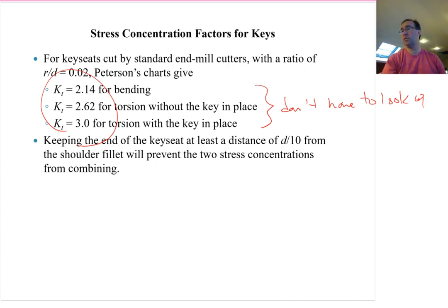Quiz question 6. And this is the other thing, you want to keep the key seat at least 1/10 of a diameter from a shoulder fillet, because you don't want 2 stress concentrations combining. That's the last note on that one.